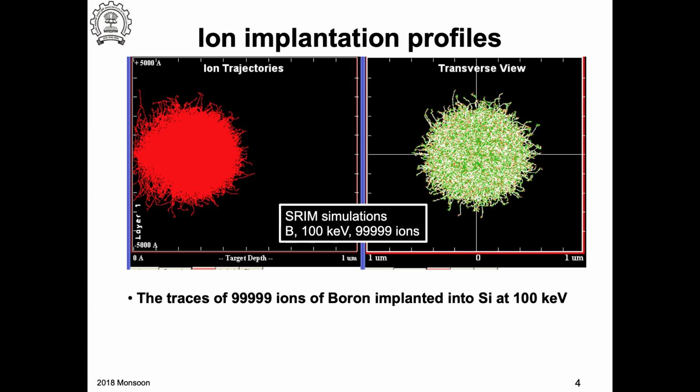Okay, so the profile is taken at which location? The point where you introduce the ions, right? So you are actually looking at this location, 0, that I mentioned on a previous slide. Injected ions at this point, and then they spread down. You are actually taking a cut along this. So that gives you the distribution of the dopants after the implant. So 10 kV is the energy in this case.